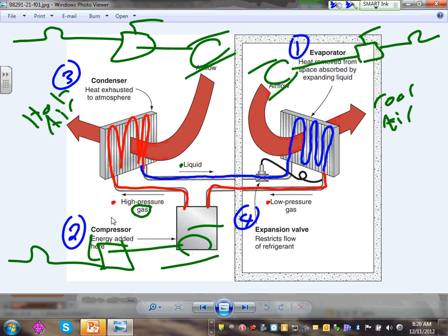Then my second job is to ask, where's your condenser blower? You need a blower for the condenser. I need to wire it. So you provide a circuit with a disconnect and a conductor to the blower that blows through the condenser, right? And then the third component is, where's your compressor? You need the compressor motor, so you need to power the compressor. Sometimes they power these two together in smaller units. You see that the condenser blower and the compressor are powered from a 120, 240 volt, 30 amp circuit typically, right?